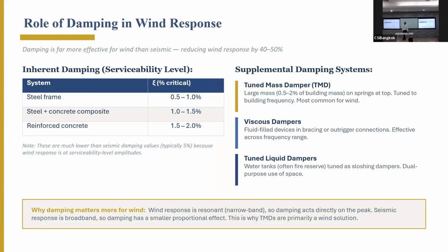So then comes damping, because damping, as you know, is important when we have dynamics, and when we have crosswind, it's purely dynamic response. So now damping becomes very important because the structure is moving just like it's moving in an earthquake. That means you have the same mass-acceleration, damping-velocity relationship.